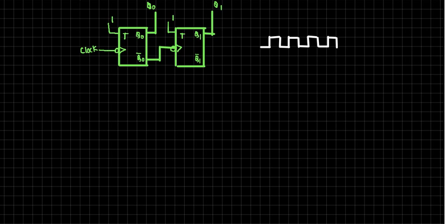You compare this Q1 and Q0 and note down all the states. You note down Q1 and Q0 for each and every transition. You tell me the transition states. What are the states, Q1 and Q0? Initially they are 0 0. Okay, leave it. After that? Go on, you leave the previous state. 3, 1, 0, right? So it's like a down counter, right?